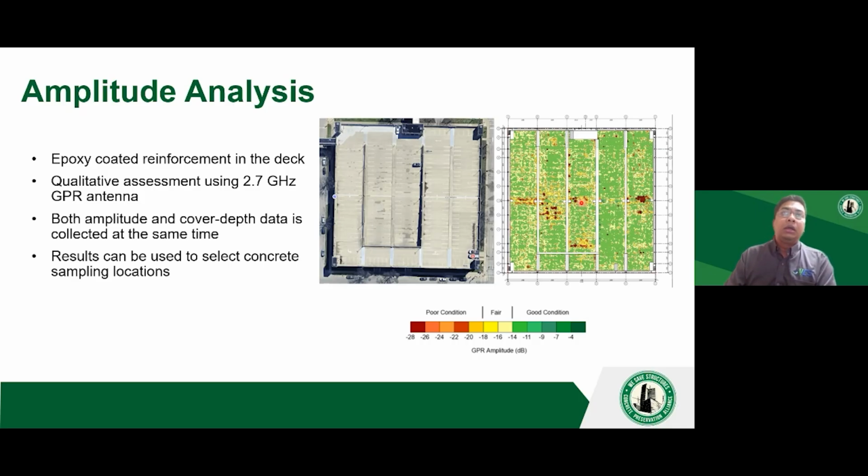Again, GPR should not be used to determine what kind of defect is present. It can only be used to tell, okay, this is the potential area where the defect is present. You need to investigate further. So this is a really good guiding tool.